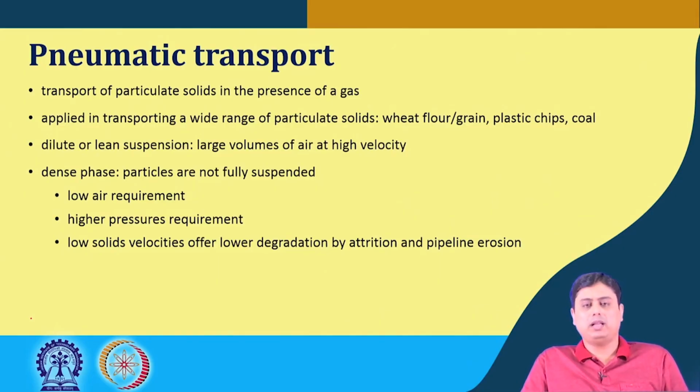Although the particles are not fully suspended, due to the low requirement of air volume, which means lower mechanical energy despite very high pressure requirement, it is beneficial in transporting the particles for, say, a shorter distance or even in a straight pipe. Why it is so, we will see when we go into the details of the flow design.